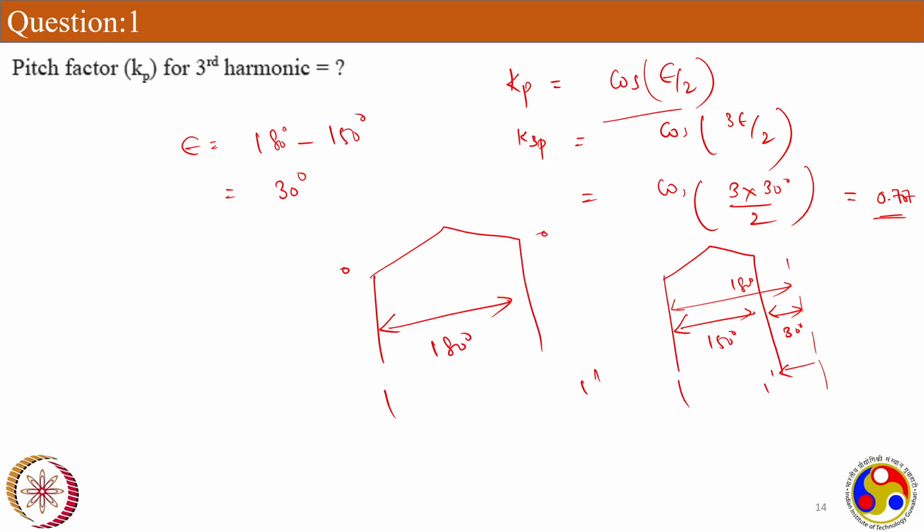of this is, as we discussed last week, if you go for less resultant voltage, you'll get to eliminate some unnecessary harmonics in the windings, and then there are many more advantages like that. Of course the resultant voltage would be reduced, but the advantage is what, so I request you to refer to the last week session that's available on YouTube.